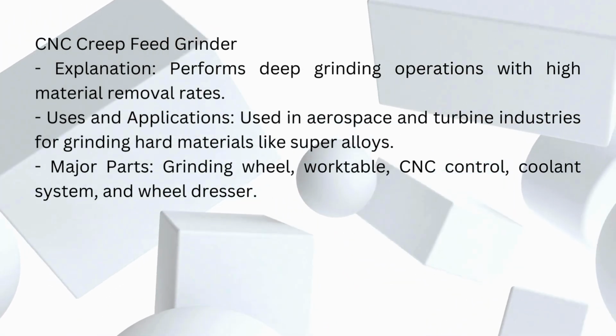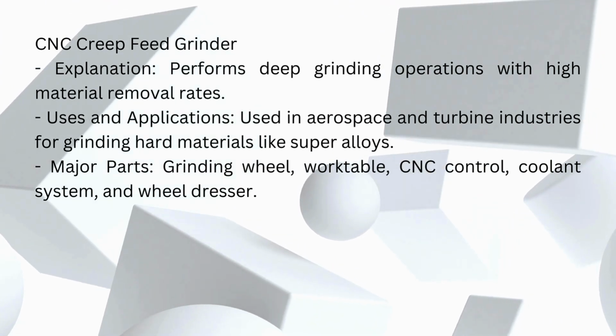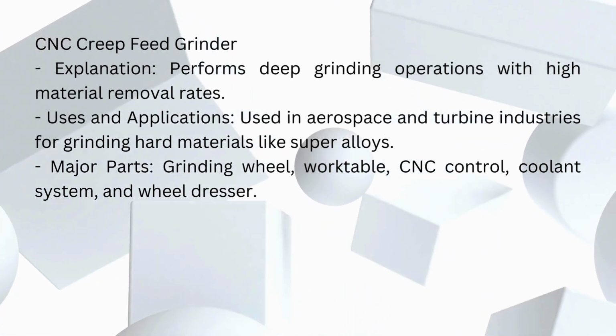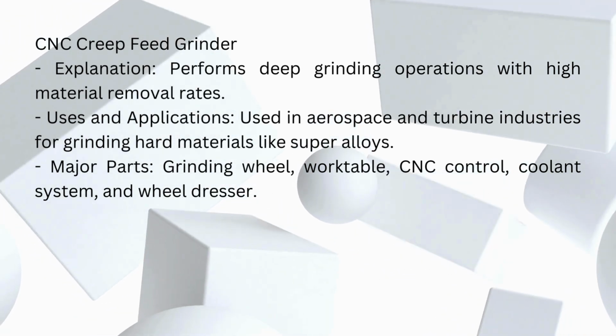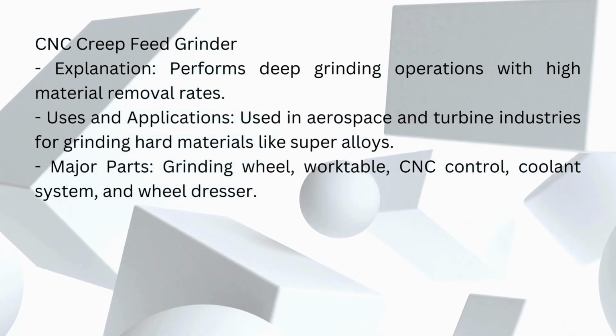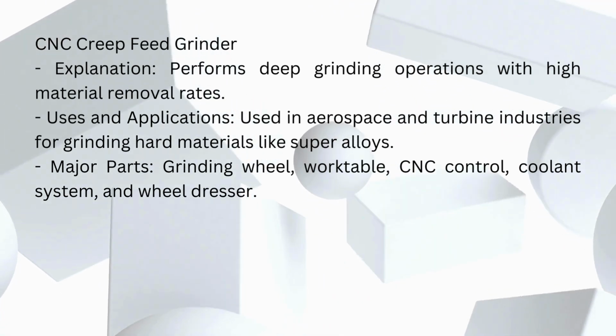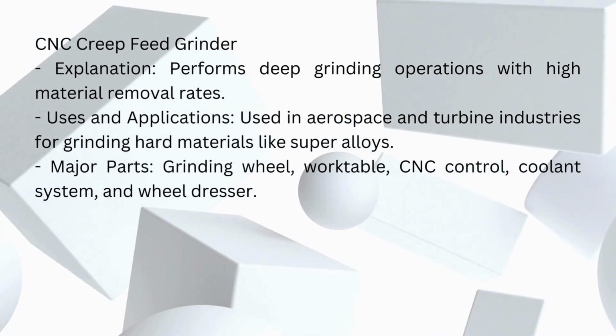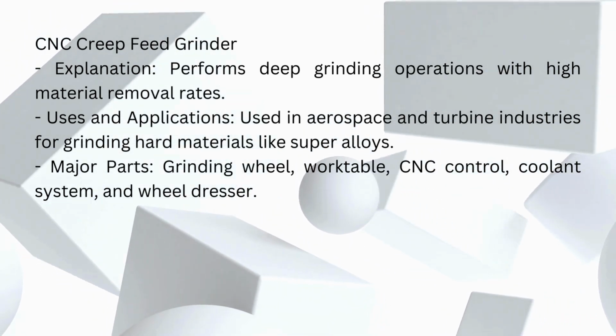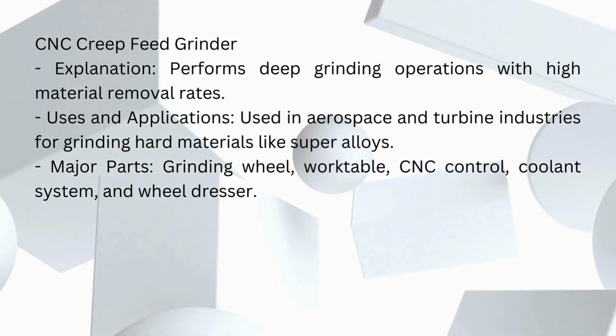CNC creep feed grinder. Explanation: performs deep grinding operations with high material removal rates. Uses and applications: used in aerospace and turbine industries for grinding hard materials like superalloys. Major parts: grinding wheel, work table, CNC control, coolant system, and wheel dresser.